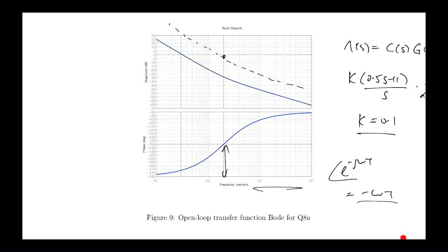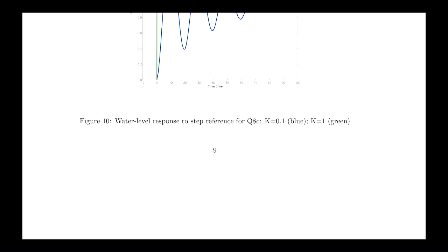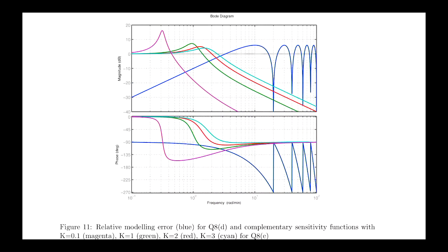It's going to pull it down eventually beyond a certain frequency, right? And eventually, when you include the delay, the phase will be below minus 180. Right? And if you want to maintain a positive phase margin, you would have to limit how far to the right you push the crossover frequency. Okay, but we're seeing the same thing now via the small gain theorem.